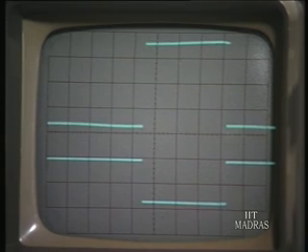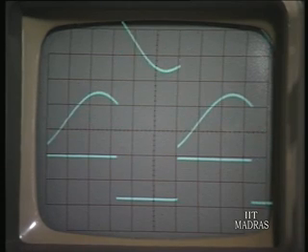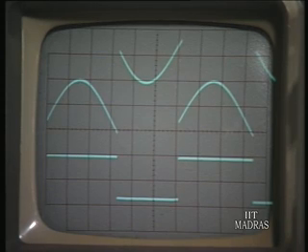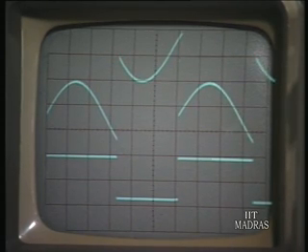So it has not eliminated anything at all, and therefore the output is simply a square wave for an input which is a square wave. This is a notch filter. It is really tuned only when it is tuned exactly to the omega naught of the filter. It will remove the fundamental and not otherwise.